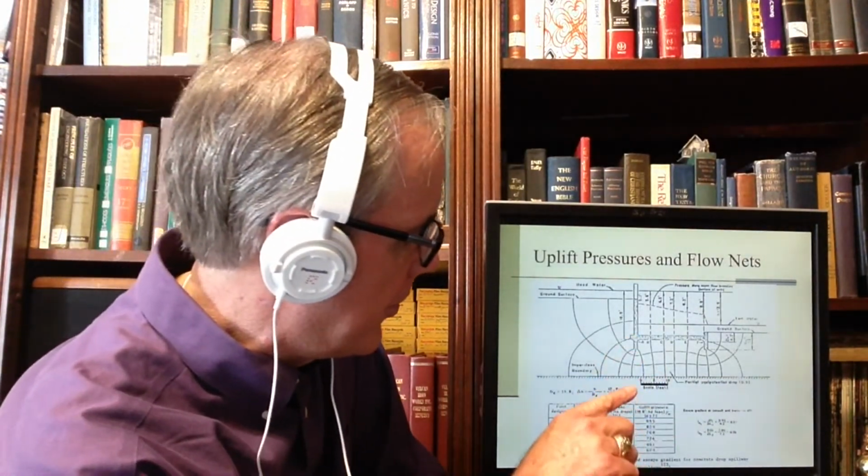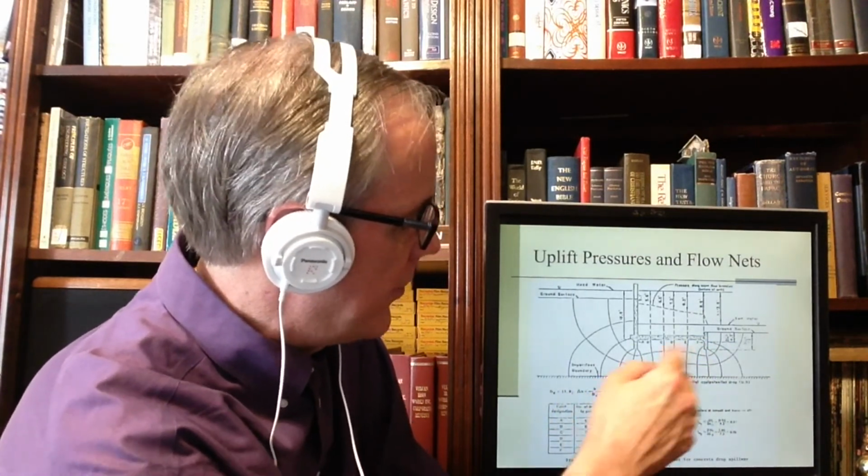Again, I don't normally spend a lot of time on this. Usually the Corps of Engineers' methods of doing this basically assume that the hydraulic pressure varies linearly along the bottom of this thing, and they take an average and whatnot, and you've got a force upward. This does it more by the head drop by head drop method, which is how most of the textbooks do it. So with that in mind, that's what we have for why hydraulic gradient is important in terms of uplift pressures.